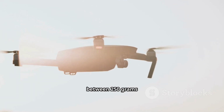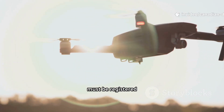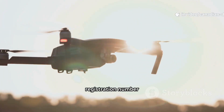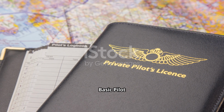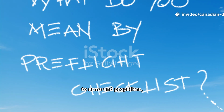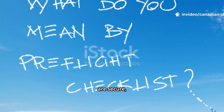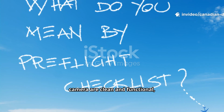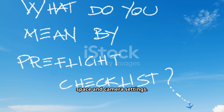If your drone is between 250 grams and 25 kilograms, it must be registered with Transport Canada, and the registration number must be clearly marked on the aircraft. You must have your basic pilot certificate with you when you fly. Perform a pre-flight inspection. Check for physical damage to arms and propellers. Verify battery health and cell voltages. Ensure propellers are secure. Confirm sensors and camera are clean and functional. And check SD card space and camera settings.